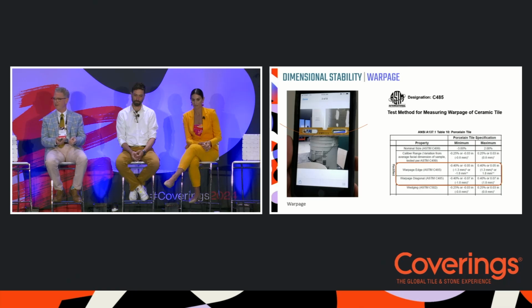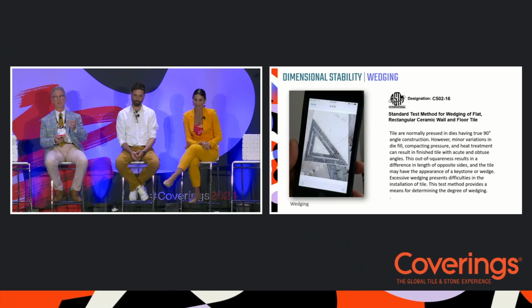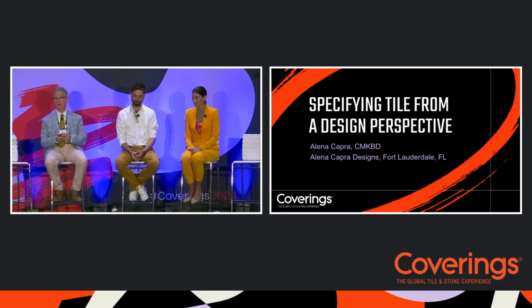This tile was a substitution from the tile specified. The tile specified was an ANSI A137.1 tile, but the owner thought they could save a lot of money by importing tile from a country that doesn't have the same ANSI standards we do. Same tile setter, Froggy, same job, same phone. Another issue, the same tile was not square. So huge, huge headache for the installer.